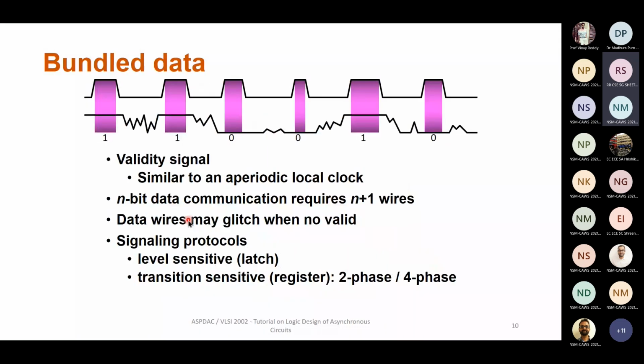In bundled data, this problem goes away because you just have a valid signal. The second stage comes to know that it is getting new data when a valid signal comes. The valid signal can be thought of as a replacement for a clock in an asynchronous design.